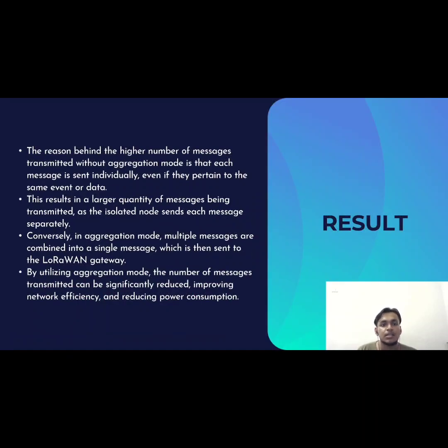The reason behind the high number of messages transmitted without aggregation mode is that each message is sent individually, even if they pertain to the same event or data. This results in a larger quantity of messages being transmitted as the isolated node sends each message separately. Conversely, in aggregation mode, multiple messages are combined into a single message, which is then sent to the LoRaWAN gateway. By utilizing the aggregation mode, the number of messages transmitted can be significantly reduced, improving network efficiency and also reducing power consumption.